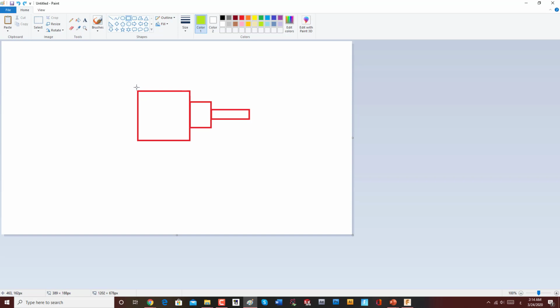Sometimes we need to buy raw material that's wider, where the diameter and the length are more, like this. So sometimes you have to keep stock here and stock here. Why? Because we need to make the surface smooth using the machine. So this will be removed by the machine, and the facing, you will do facing from the face here, will be removed. So what's the size of the stock? The size of the stock is from here to here.